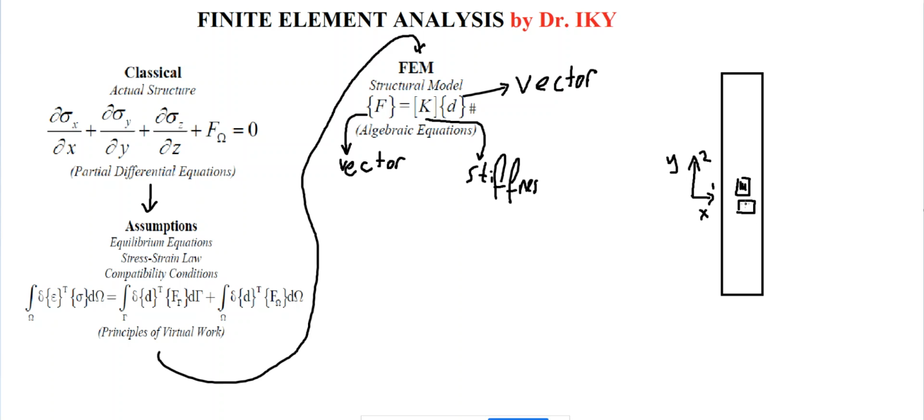I'm sorry, I have drawn in the wrong direction. Yes, for this direction, this strain gauge will give you the results. For the direction 2, you will get the results with this strain gauge, or the digital image correlation or laser extensometer, etc. So this is going to give you an ability to find out the Poisson ratio of 1, 2.